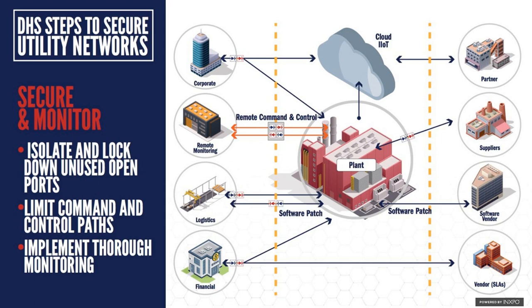a two-way connection that I absolutely have to have, and we all know those exist. And probably the only use case where you don't have that is nuclear power plants, where they've completely isolated and they're truly one-way out only. But I do have a remaining two-way connection that I'd like to use and you need to use. The recommendation is to lock that down, close any unused ports, and limit the command and control connections, what's actually going to occur on there. And then you've got your intrusion detection systems, and all the other threat mitigation and threat analysis resources that you can now apply to this connection.